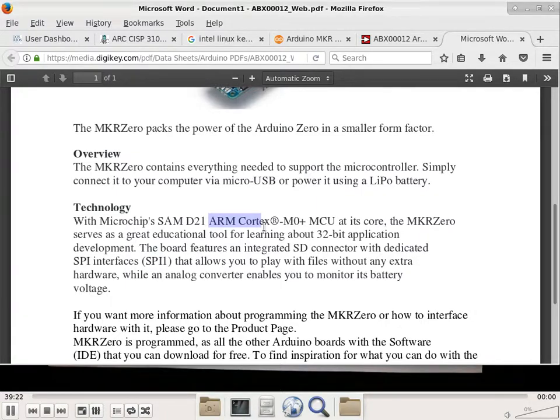Go ahead. Is there any way to make a second stack within your primary stack, or the only stack? Yes. So what you're talking about is related to multi-threading. In multi-threading, every thread has its own stack. But when interrupts happen, if it's not in protected mode, the interrupt will just use the stack of whatever thread is active at that time.